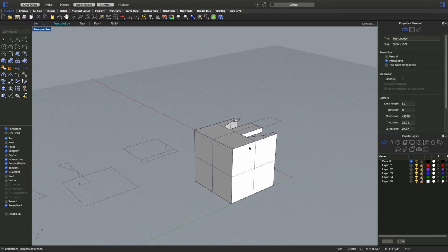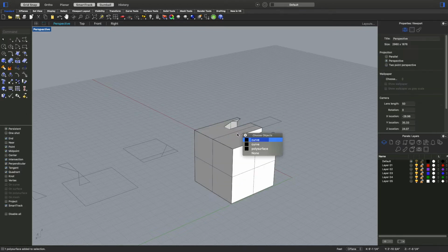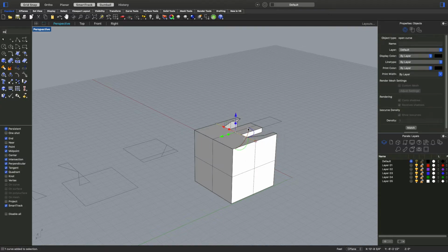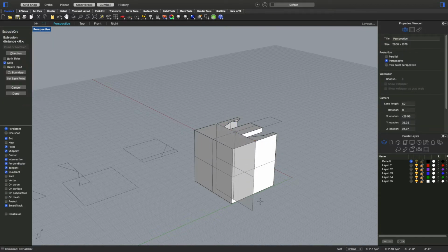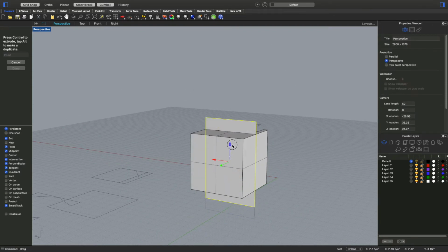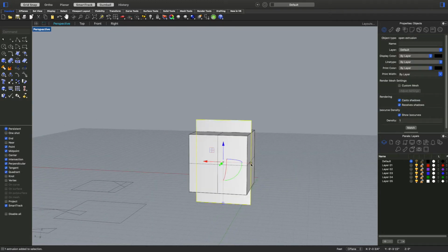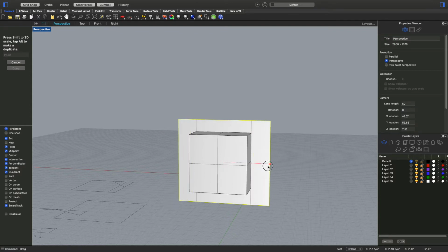But we've got this back end that's 3 inches too deep. So what we want to do is cut it off. And I'm just going to cut it using a plane here. So if I draw a line from that midpoint to this midpoint, click on that line, curve, right there, extrude curve, go all the way through. Now I've got a cutting blade. I plan on moving this up. And then I'm going to actually use my scale function to make it wider. I'm just making it bigger than the area of the object there.